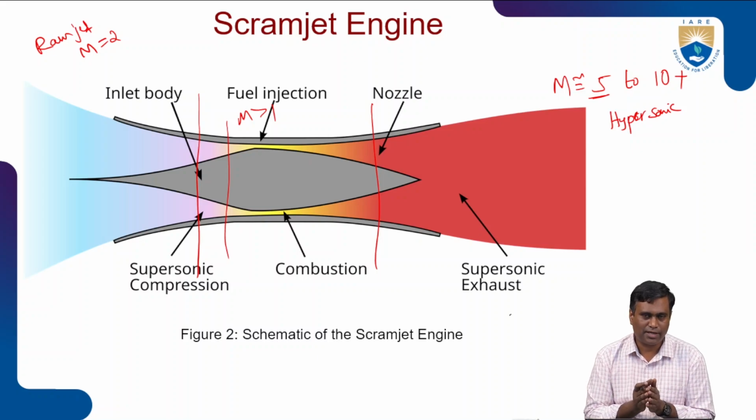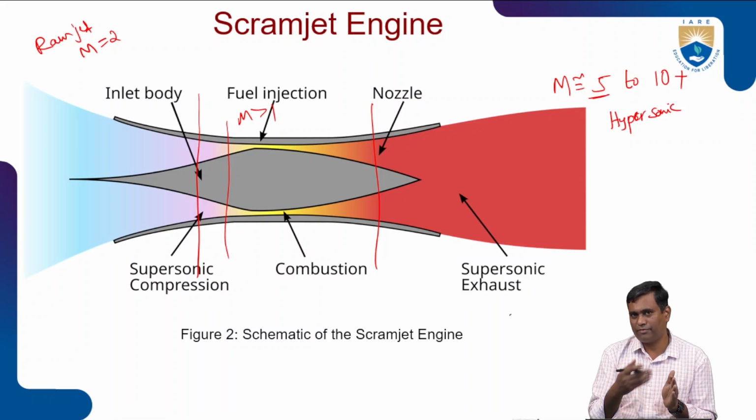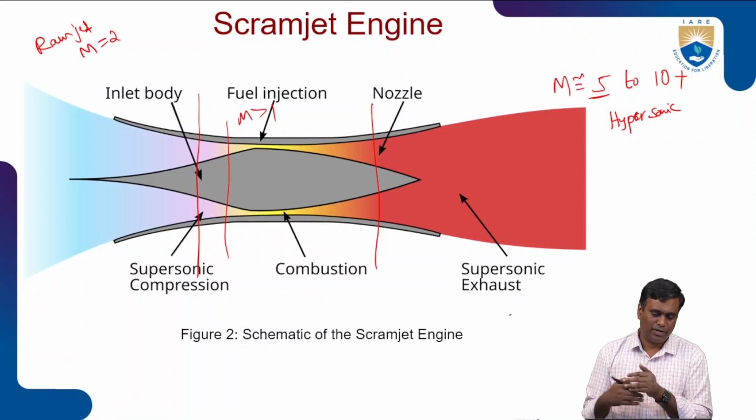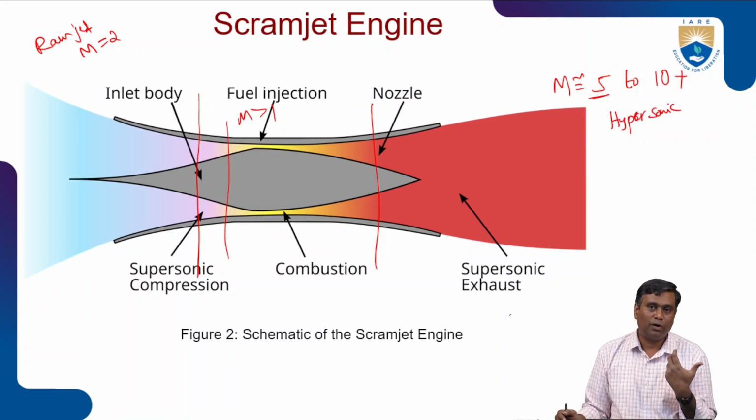In both the cases, or especially in scramjet, fuel injection and taking place of a uniform air fuel mixture, and then sustaining such huge temperatures also matters. And especially in ramjet engine development and testing and scramjet engine development and testing, there are many failures. There are many failures due to failure of structural components.